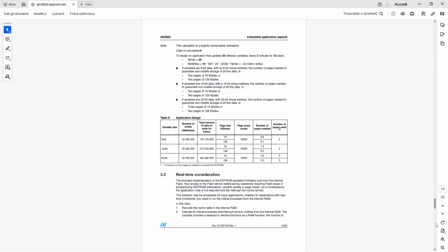Again, emulating EEPROM on flash must be carefully done, and we cannot simply use one flash sector, erasing its content and writing over it any time we need to update the data stored in it. So the only safe way is to use an external EEPROM.